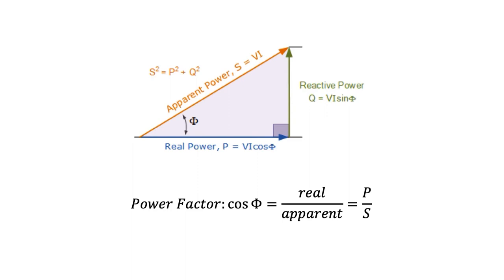If the power factor is 0, then there is no real component, and the AC circuit is either capacitive or inductive, depending on which power component is larger. If the power factor is 1, then there are no imaginary components of power, and the power is solely due to the resistor consumption.